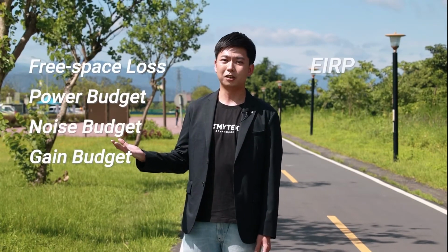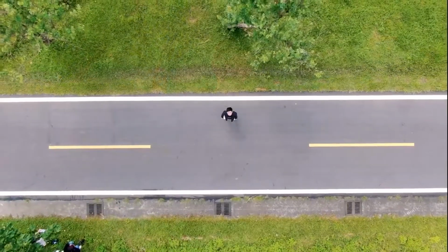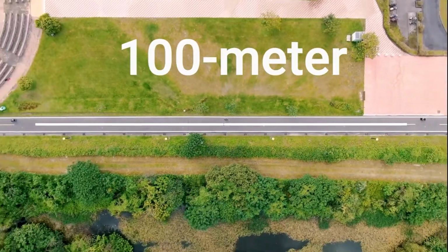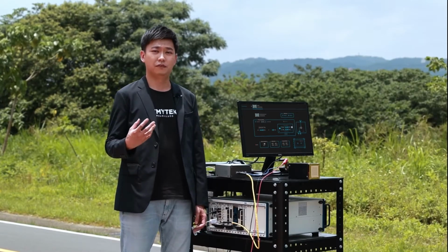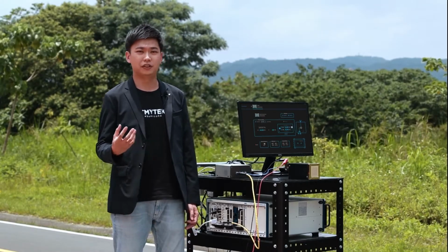For system evaluation, some of the important parameters we should know are free space loss, power budget, noise budget, gain budget, EIRP, and TRP. And finally, the system characteristics are usually based on SNR and EVM. In this section, we will demonstrate the 100-meter outdoor scenario. The most important parameter we are focusing on here is EVM. The lower the value of EVM, the better the transmission quality. Let's see how we evaluate the link budget in this case.